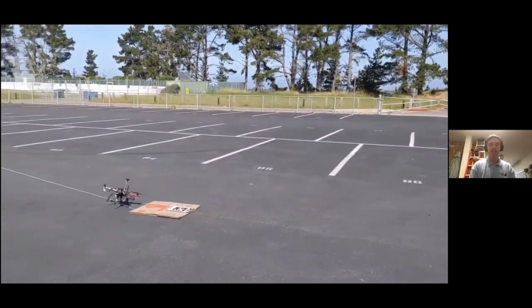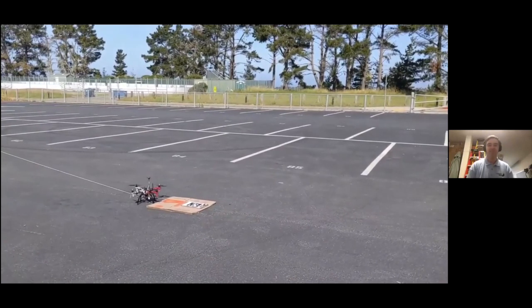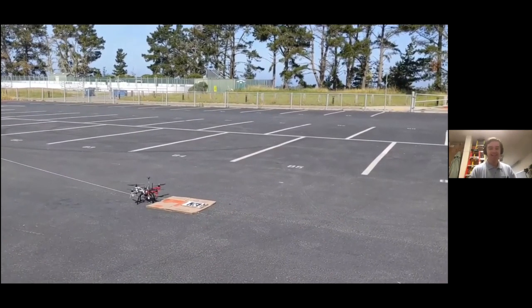Only in the last quarter meter does it lose sight of the tag. It loses sight of the tag because the tag at that height versus the vehicle is such that the entire camera field of view is taken up by the tag. And unless the camera can see the whole tag, it will not register the tag and make any detections.